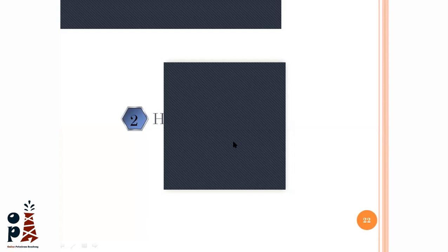Okay. If it is an exploration well, we call it a wildcat well. Why? Because we don't know what we are going to have. So in the exploration or wildcat well, we have to install the diverter, which is used before installing the BOP. And in case we have shallow gas or a sand lens and there is a kick or uncontrolled fluid flow, we have to divert it away. And in case we are already using the BOP, we have to close the well and calculate the kill mud weight and use a higher mud weight, because if we don't do this, we cannot continue drilling. So we have to increase the mud weight to face this overpressure.